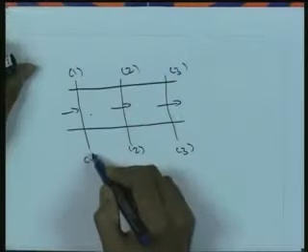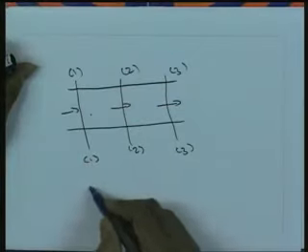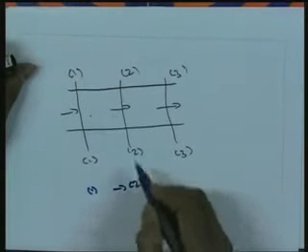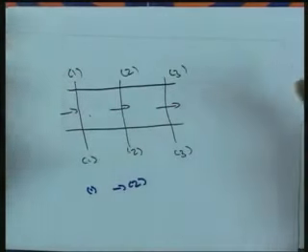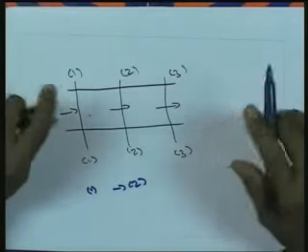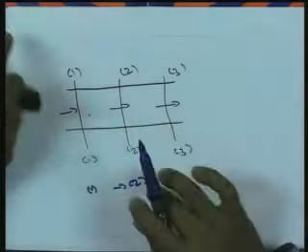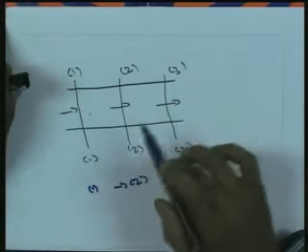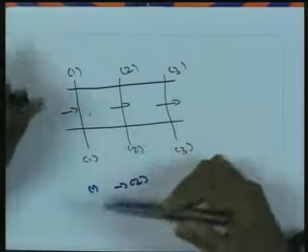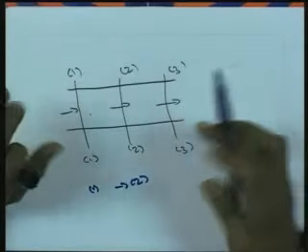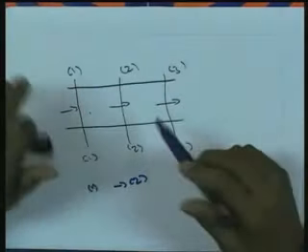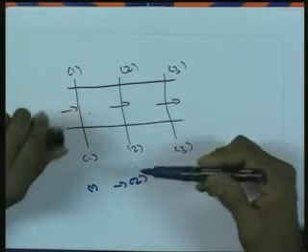But as far as non-uniform flow is concerned, a flow is said to be non-uniform when we go from section 1 to section 2 and the flow parameters like velocity, pressure, and all these parameters change with respect to space. So when we consider fluid motion spatially, if the velocity, pressure, depth, and other parameters are changing, then that is called non-uniform flow.